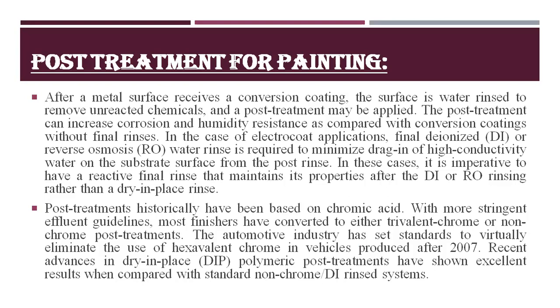In the case of electrocoat applications, a final deionized or reverse osmosis water rinse is required to minimize dragging of high conductivity water on the substrate surface from the post rinse. In these cases, it is imperative to have a reactive final rinse that maintains its properties after the deionized or reverse osmosis rinses rather than a dry in place rinse.